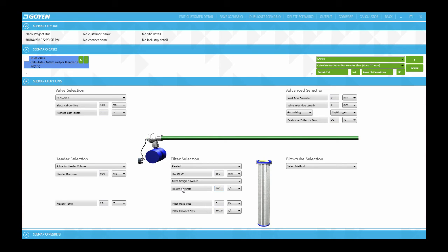The next field to be input in the filter conditions section is the pressure drop, this field here. The pressure drop is the difference in pressure between the incoming dirty or particulate laden air and the clean or filtered air passing out of the filter house or filter assembly. The pressure drop is identical between the inlet and outlet of the filter house and that from the dirty to the clean side of the filter bag. It is to be thought of as merely the pressure difference between these two extreme points in the filter process.